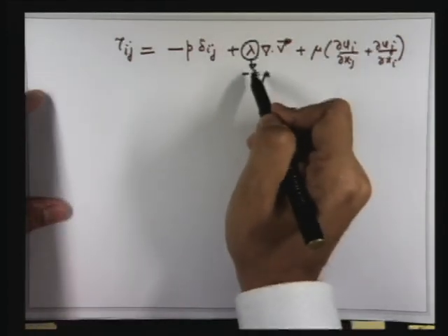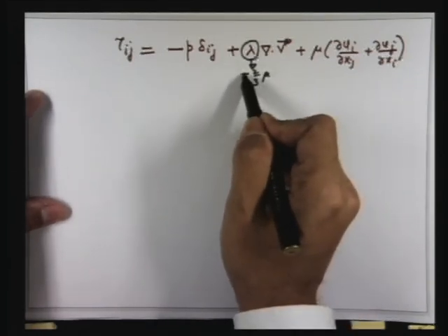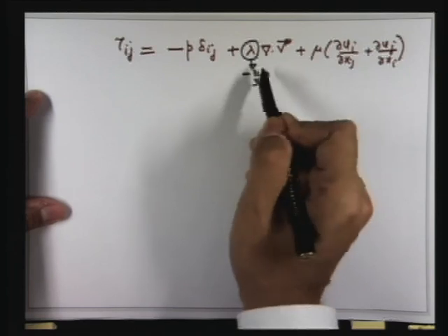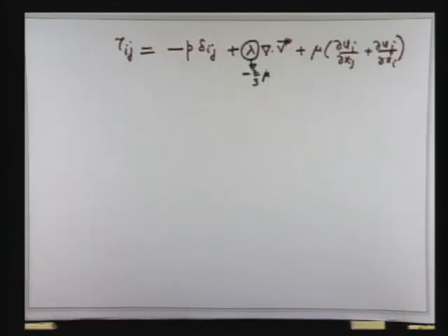Now see, there is another interesting thing. There is a lot of physics associated with the term that you have a minus, positive, negative, right? That means physically, for a fluid element which is already stretching, the incremental stress required to stretch it further is negative. That is, you require less stress to stretch it further if it is already stretching. That's why this negative term appears.